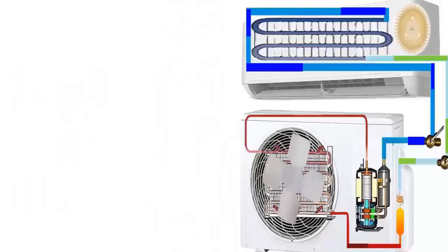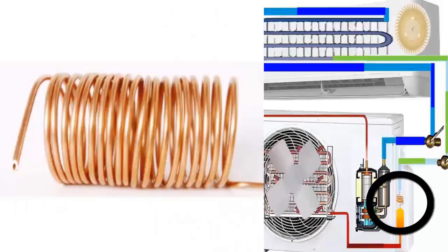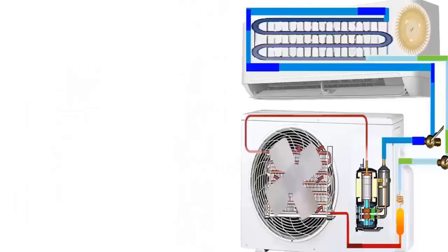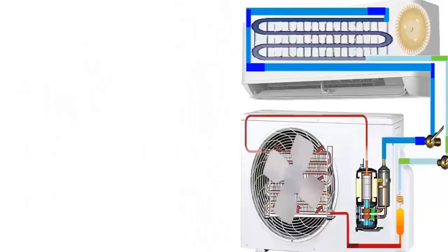14. There may also be an internal blockage in some pipes, preventing the refrigerant from reaching the indoor unit. Pay attention to the capillary tube. If ice forms or it is excessively cold, this could be a sign of an internal blockage at that point. Check for bent pipes that could restrict refrigerant flow, and verify that the valves in the outdoor unit controlling the refrigerant flow are open.